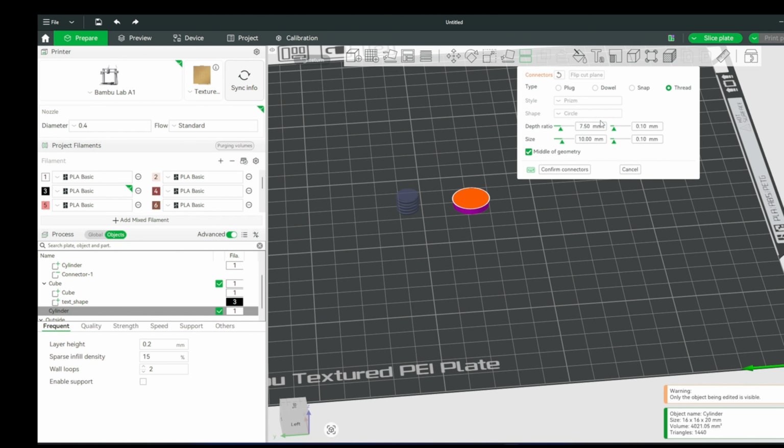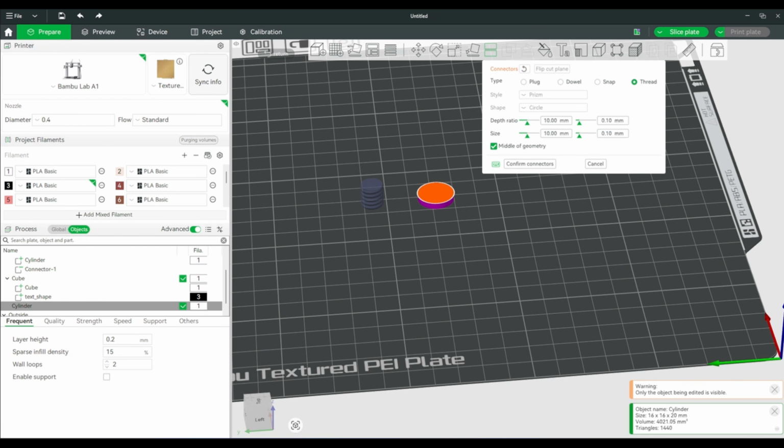Set this exactly to 7.5 millimeters, based on our golden pitch formula calculation. 1.5 millimeters pitch times 5. Now let's talk about tolerances. As we already discussed and thoroughly tested in my last video, if you are making both the bolt and the nut out of 3D printed materials, whether you are using filament or resin, the best clearance values to use are 0.1 millimeters or 0.2 millimeters.